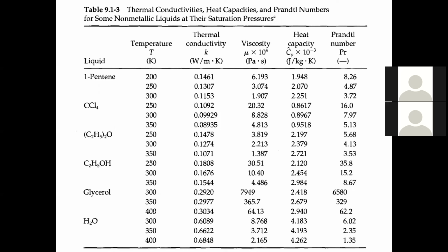It's quite important to think about here, because we're going to talk about heat transfer. Heat transfer happens because of differences in temperature. So this is non-isothermal. There's no isothermal transfer anymore. So technically our thermal conductivities could change from location to location simply because I have different temperature. Now we're going to assume that temperature differences are not high enough, or that we can freeze this thermal conductivity value for the moment. But that's an assumption.